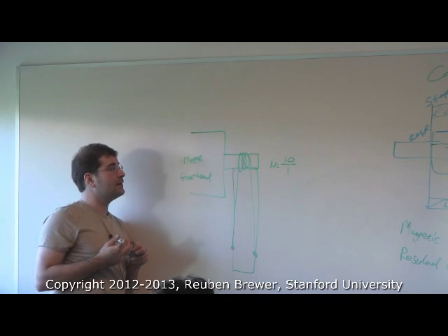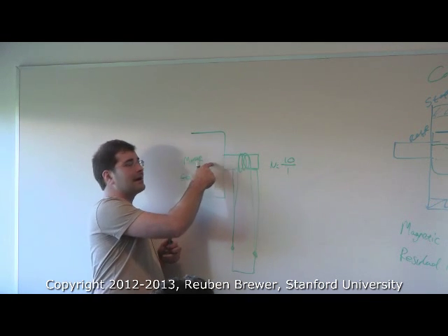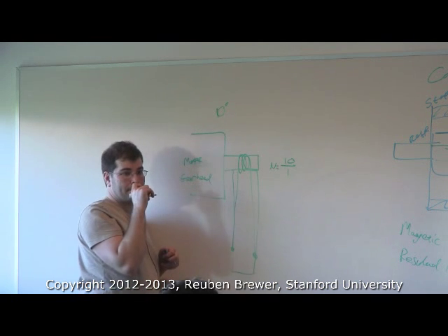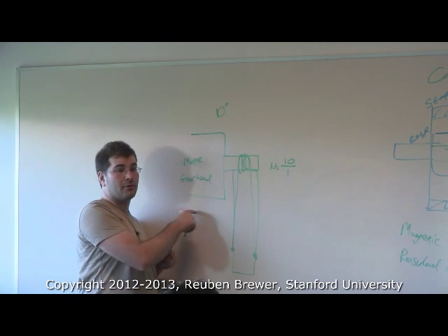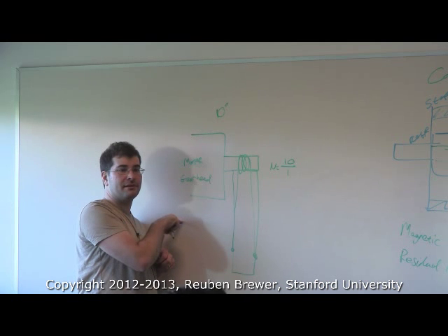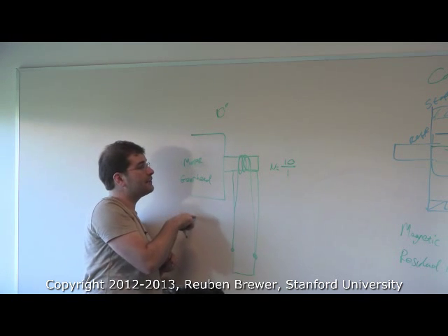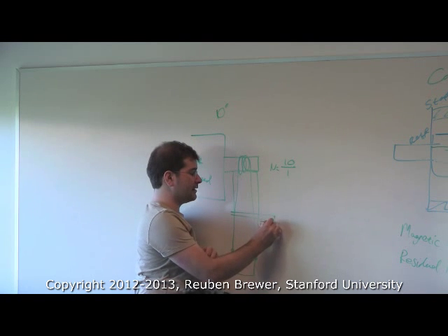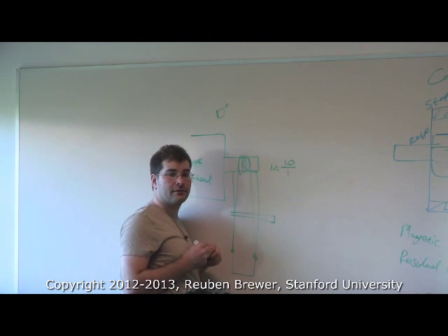Okay. Now let's say that my cogging happens every 10 degrees on the motor. Cogging is not independent of gear heads, it's just in the motor. So how many degrees am I going to experience cogging on this cable shaft? 100?